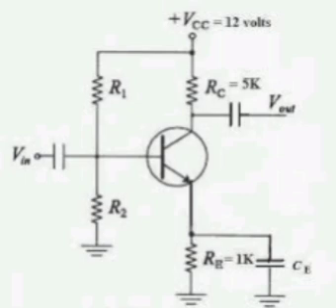VO2 equal to minus 1 by SC by R into VO1, that equals minus VO1 by SRC. For A1, V plus equal to VO2 by SC whole by R plus 1 by SC, that equals VO2 by 1 plus SRC, that equals minus VO1 by SRC into 1 plus SRC. VO1 dash equal to 1 plus 1 by SRC into V plus, VO1 dash equal to 1 plus 1 by SRC into minus VO1 by SRC of 1 plus SRC, SRC of 1 plus SRC in the denominator part.